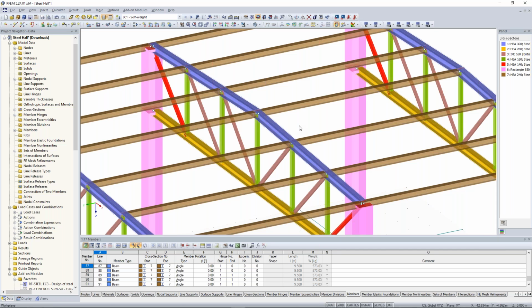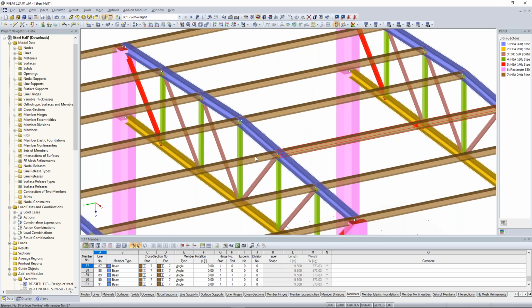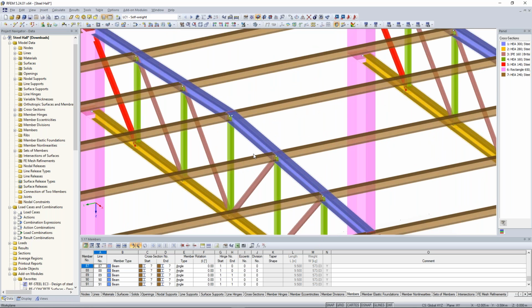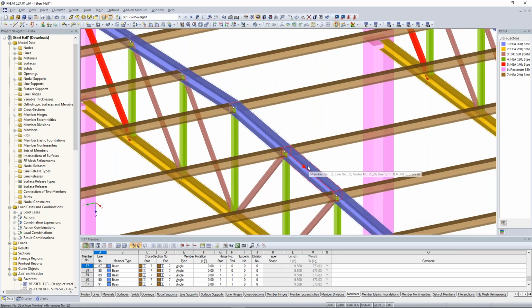So when this continuous beam gets some loads, yeah, it will have a distribution of a moment, something like that. Yeah, so a support moment and a field moment, and I want to transfer only shear forces to that beam, to that upper chord.